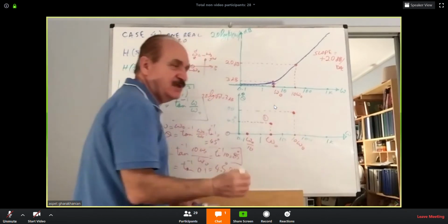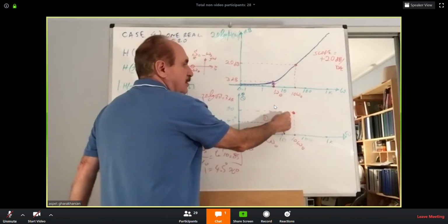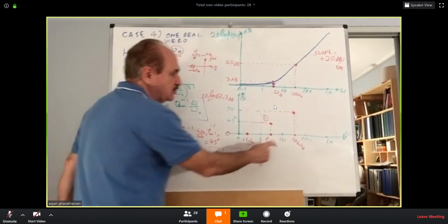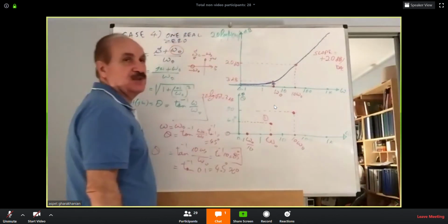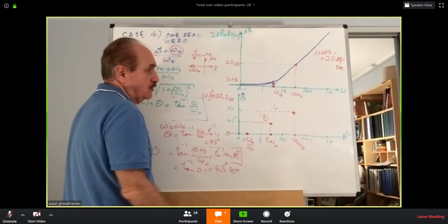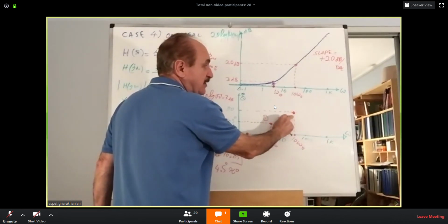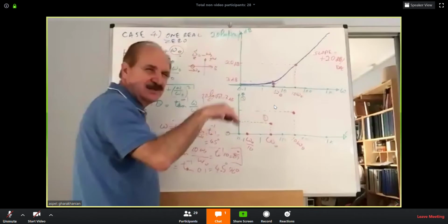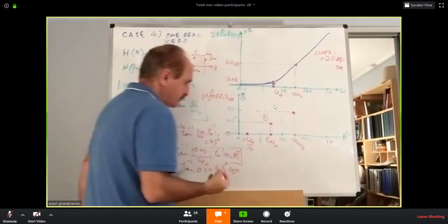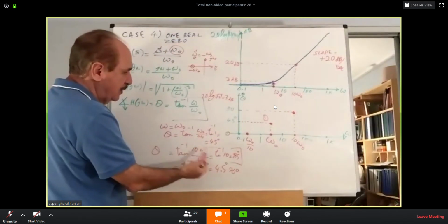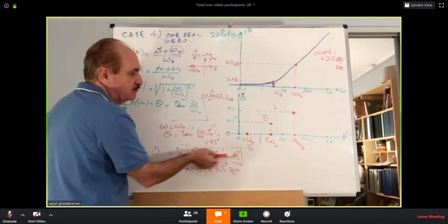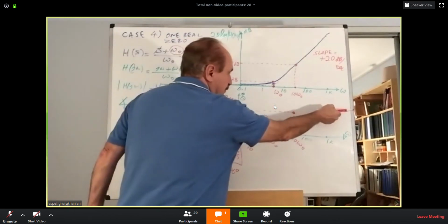This is the crude placement of the angle at a frequency equal to 10 times the cutoff frequency or the break frequency. But we know it is not 90, it's actually 85. So it's 5 degrees under. Then after that, what happens? Obviously, if you go to 100 times omega O, this angle will approach asymptotically towards 90 degrees.